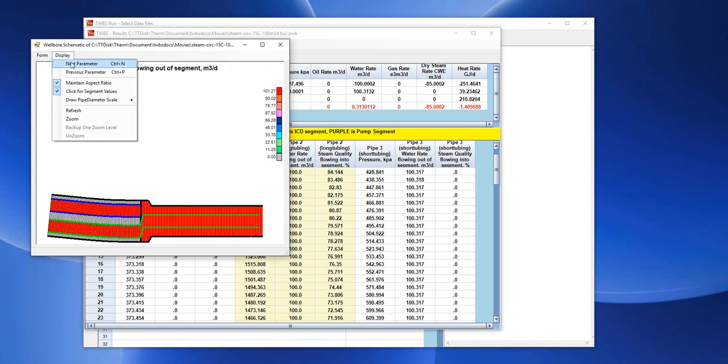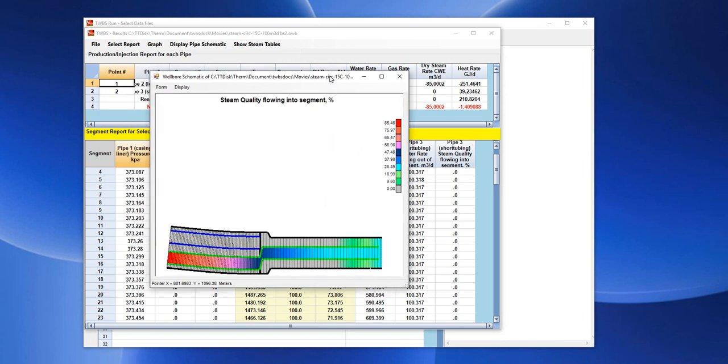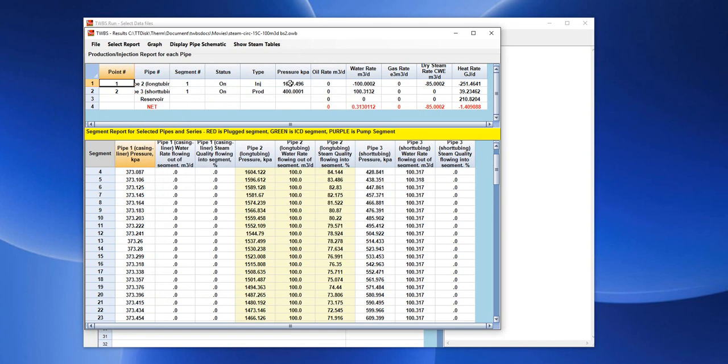The steam quality is decreasing as it goes through the long tubing, and as it returns along the annulus, it condenses to water and returns essentially as water. And the model is showing us that for the cold reservoir, the data says okay, except that our pressure difference needs to be higher in order to be able to return that head of water.